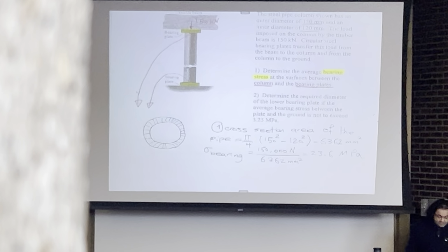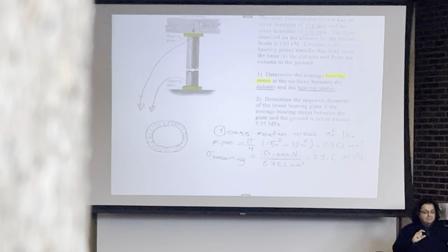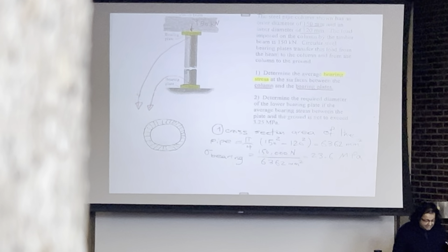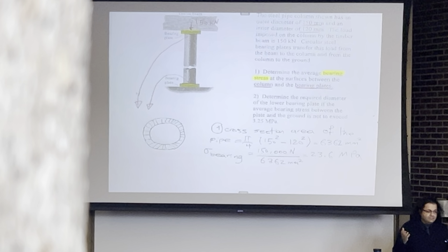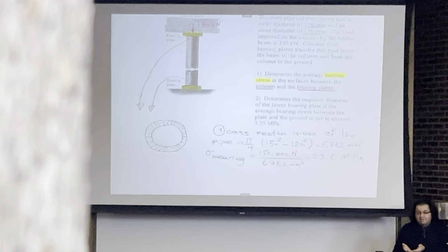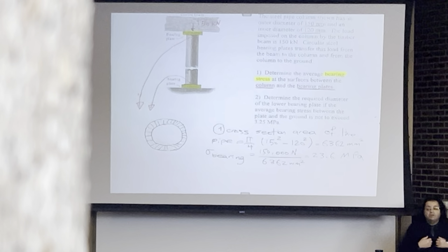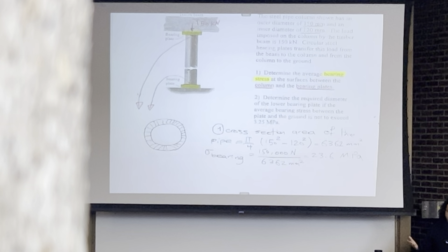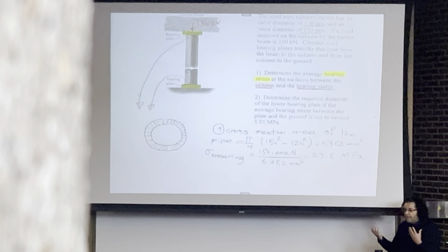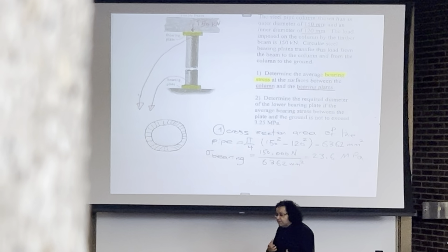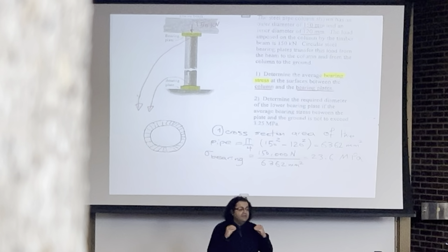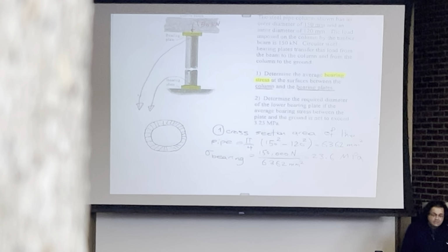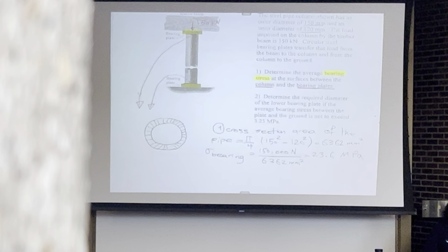So the first part was an analysis problem, where we calculated the stress. The second part is a design problem. The allowable bearing stress is given and we are required to calculate the area, or design the bottom plate. This is also an important design that should be done by a structural designer. Design of the plate is one of the jobs that a structural designer should accomplish.